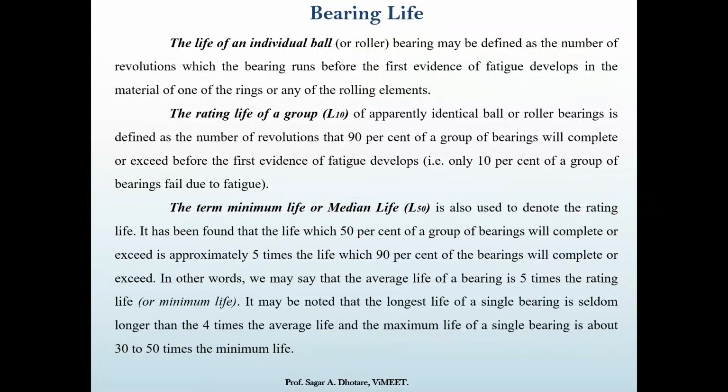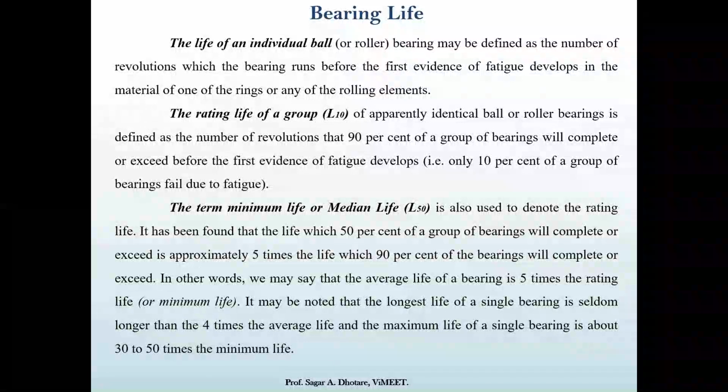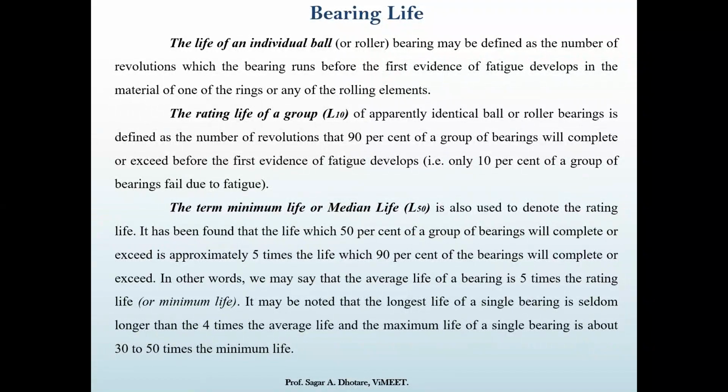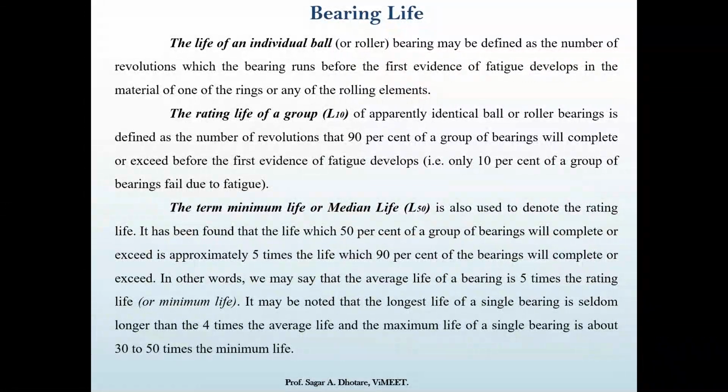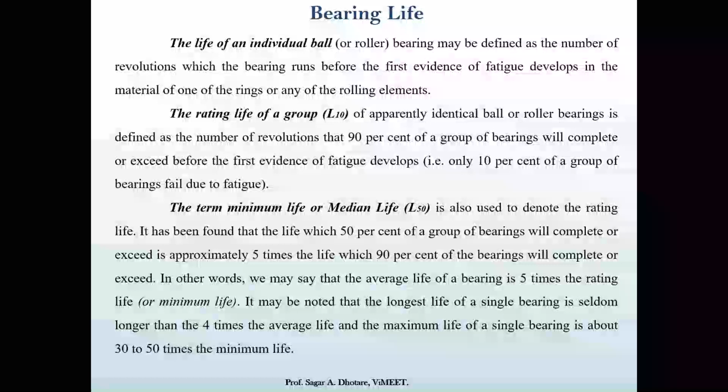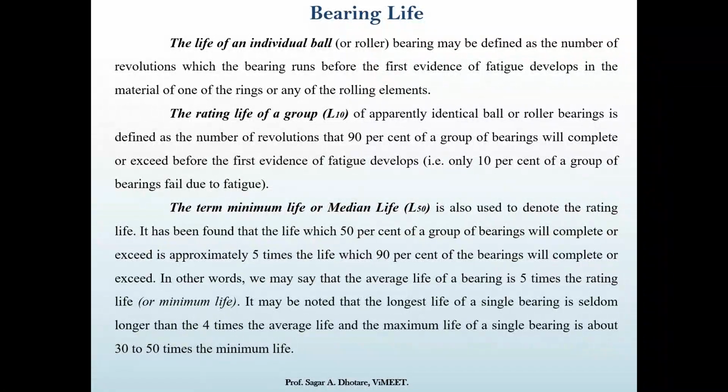If any component, that is a ball, race, or cage, develops even a small, minor crack, then the bearing is not suitable for the selected application, so we need to change it.